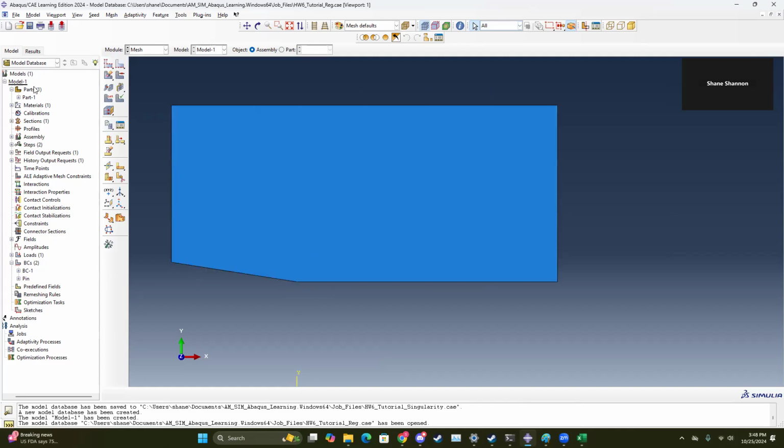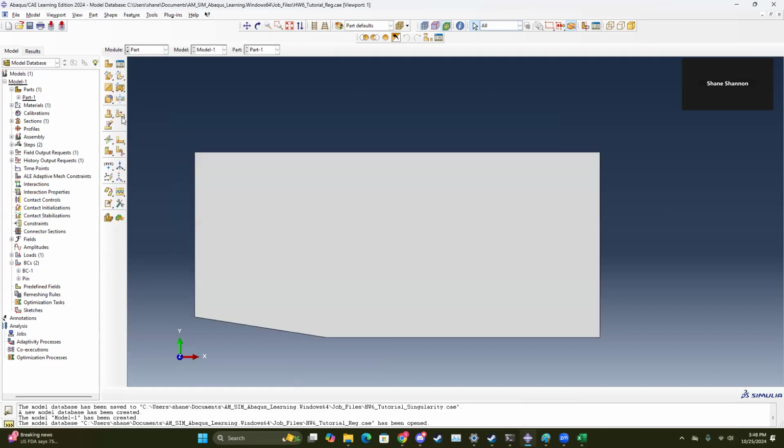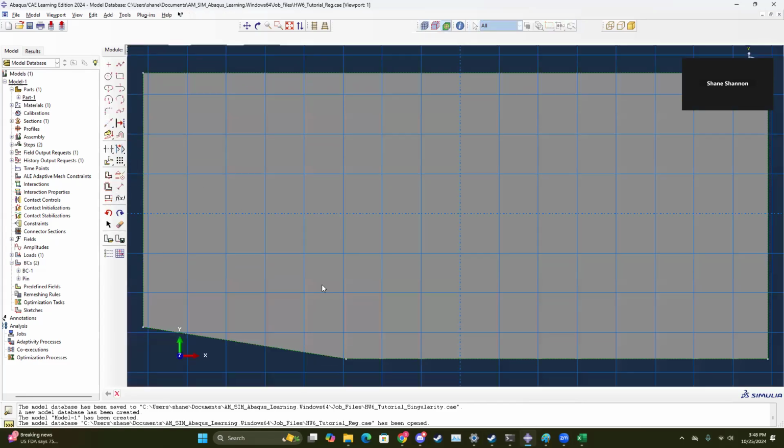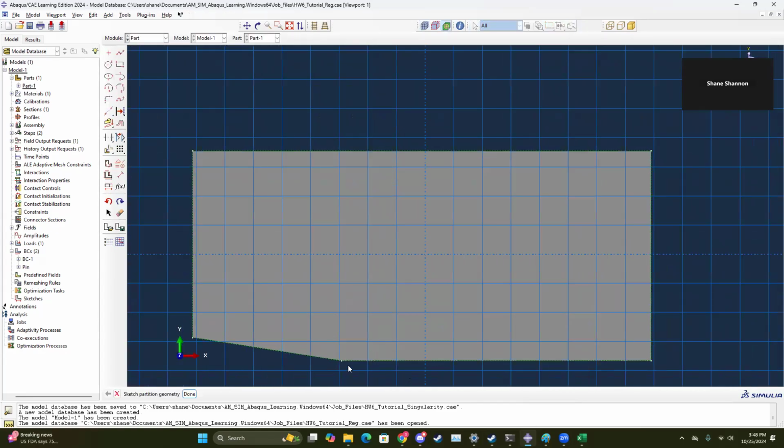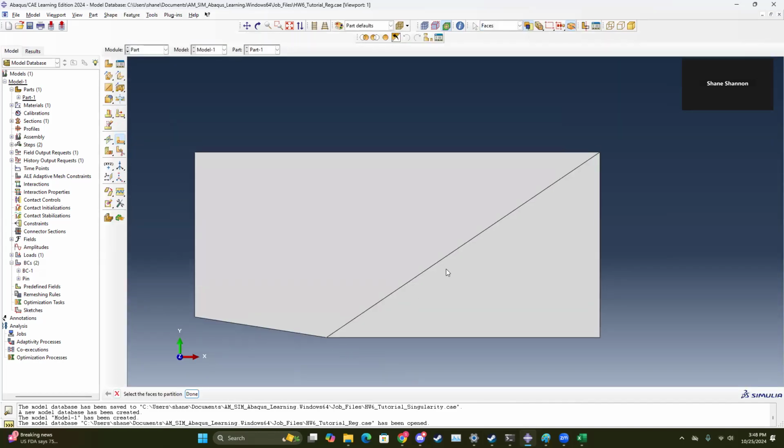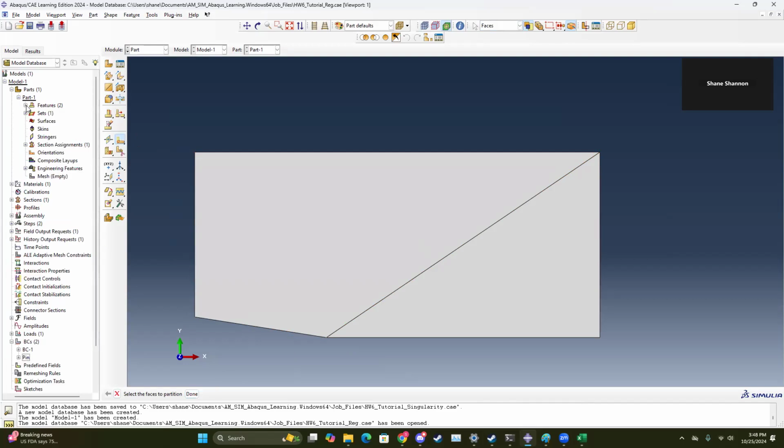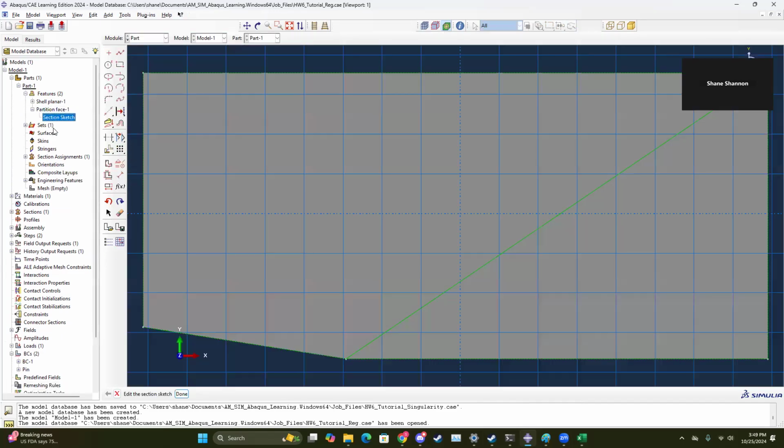So with that, I'm going to create a partition to help define the mesh and shape it. Here to here, a partition geometry, which will come in handy in a second. Now it's two different spaces, and I've got a line going down and able to create any of these partitions using this button here. It'll show up in the tree as a separate feature, so if you need to go back and edit the sketch itself, you can do that.